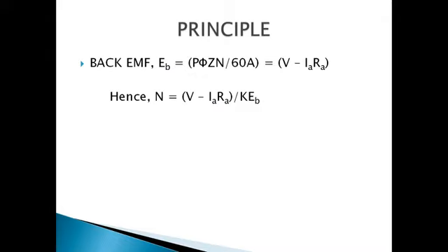As we can see from the relation, the back EMF induced is proportional to locomotive speed. So at a certain speed, the back EMF increases and becomes equal to the input voltage. Both these forces try to nullify each other and hence the engine starts to decelerate. To counter this, we need to decrease the back EMF. This is achieved by transition, in which the traction motor windings are changed from series to parallel at certain specific speeds.